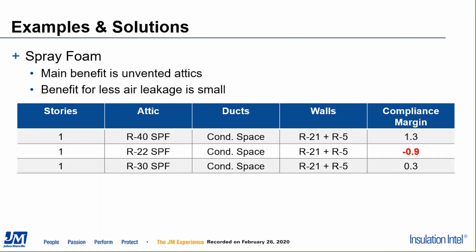What if we want to put less than R40 spray foam in our attic? What if we bring it back to that mandatory minimum of R22? Well, now we don't quite get there, right? That red shows that we're not meeting the code. We've got to at least do R30 or so to show compliance.